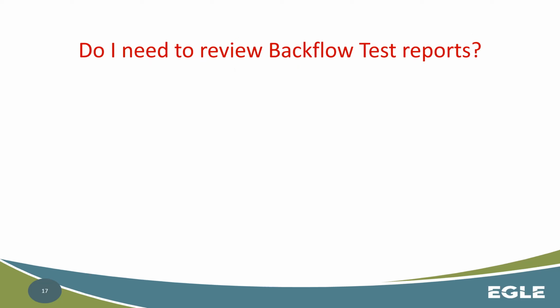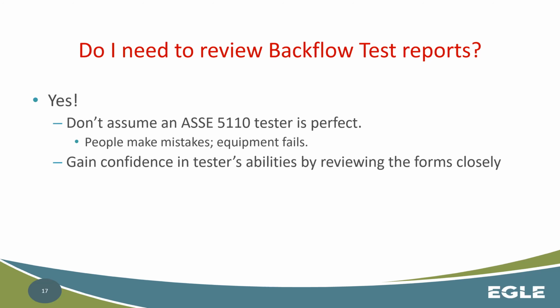Do I need to review my backflow test reports? Absolutely you do, for a couple of reasons. You want to make sure it's being done properly and adequately, that the tester is not shortchanging you. You're going to find bad testers and you're going to find good testers. I hate to tell you that, because we would hope everything's lollipops and rainbows and everyone's fantastic, but that's not the reality. Some are going to be bad, some good, even if they are all ASSE certified. By reviewing them, you will know who's good.